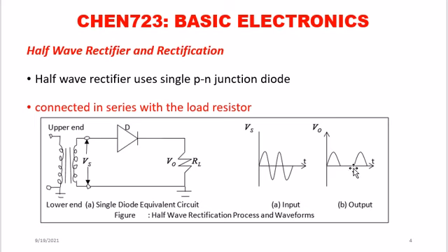It is like wasted. Now after this negative, it will go back to positive, and that positive will forward bias the diode and allow the current to flow. It will keep on doing like this. And if you look at it, we are conserving the positive half and we are destroying the negative halves. This is the reason why we call this one a half wave rectifier.